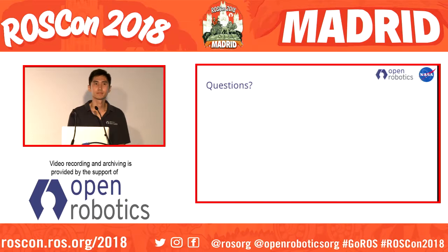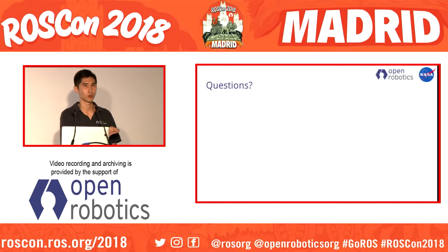How are you dealing with the physical simulation of regolith and moving through it? So on the physics side, we only have the high resolution DEM. So that's basically all we have. When we're doing all these tricks, like having normal maps and also level of detail and all that, it's not affecting the physics. So for physics, we preserve the high fidelity DEM files to simulate all the obstacles. So does that mean it's effectively moving over a solid surface, or is it more like sand? It's more like a solid surface. Okay. But with a wheel slip model through a different plugin.